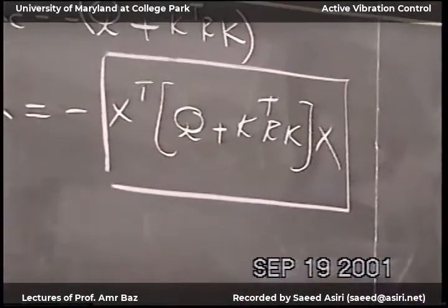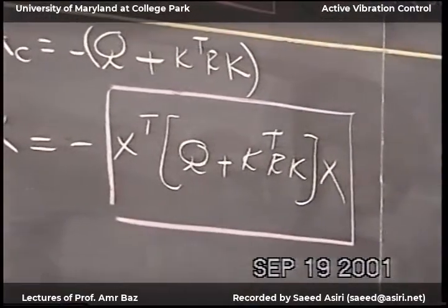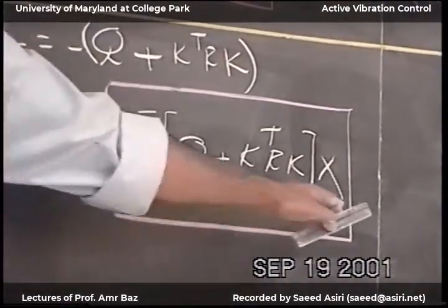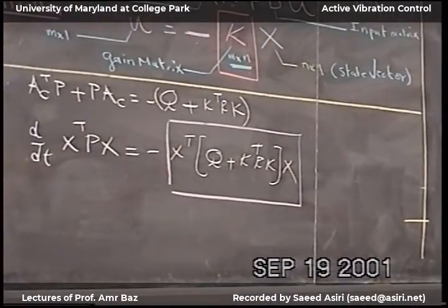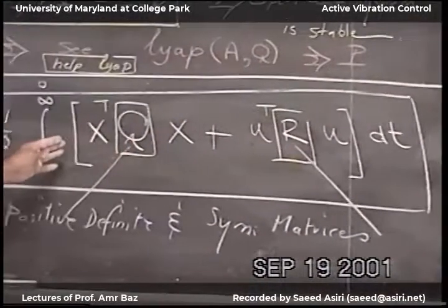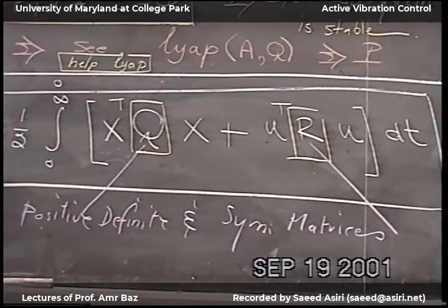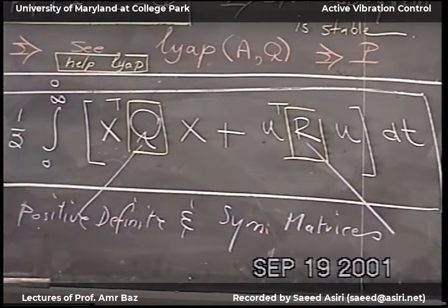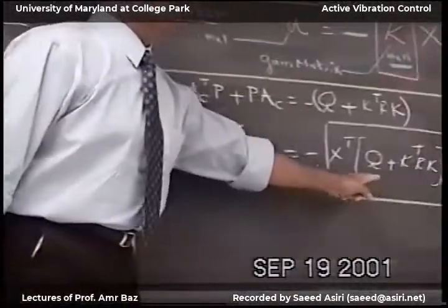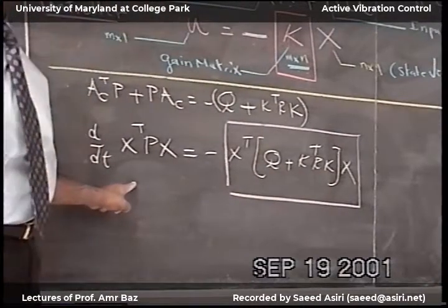Now if I want my linear quadratic regulator to give me a controller that is stable, then I better select this equal to the negative of this. That's the most powerful thing in the linear quadratic regulator. If you take the equation of the performance index and you take the result that we will extract for the control gain, automatically, without thinking, this is a stable controller. Why? Because we found the condition for stability, and I'm going to use this as we derive the controller later on.